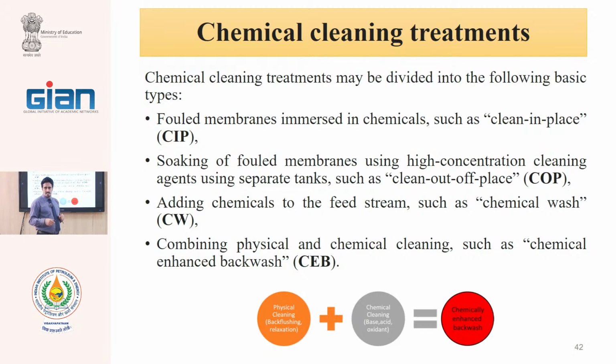we use the cleaning agent in that place, but in very bad fouling, in many cases we use the cleaning in place, but the flux does not come back. Therefore, in these special conditions, we take out the modules and go to the lab, and in the lab with different chemicals, test to recover the modules.